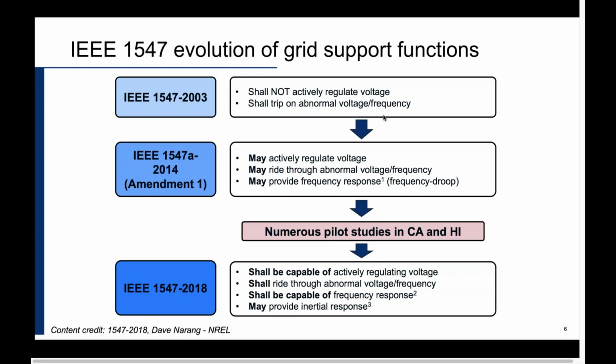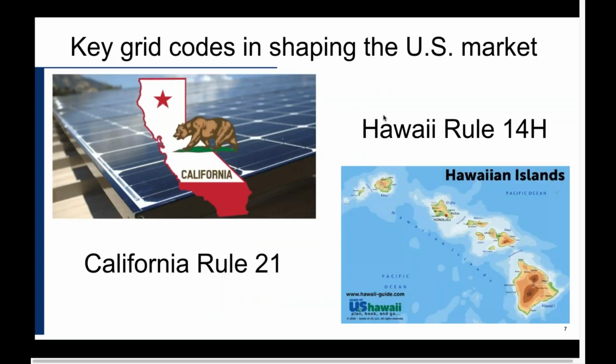Now, all these DERs that get connected shall be capable of actively regulating voltage. It should provide support during abnormal voltage and frequency conditions and should be capable of frequency response. And now it may provide inertial response. Maybe this might become a shall in the next few years.